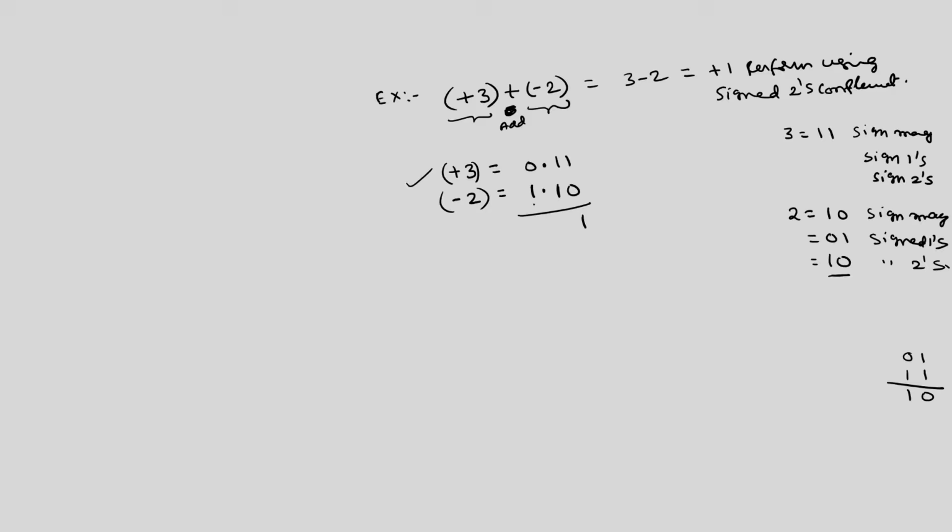This is 1, 1 plus 1 is 1 0, 1 plus 1 is 1 0. So, this overflow you can neglect, because so how many bits have you taken? 3 bits, this is a 3 bit representation. So, what is the range of the numbers that can be represented in 3 bits? The range for w equal to 3 is minus 1 as the negative number, that is the minimum number, and the positive number is 1 minus 2 raised to the power of minus of w minus 1.